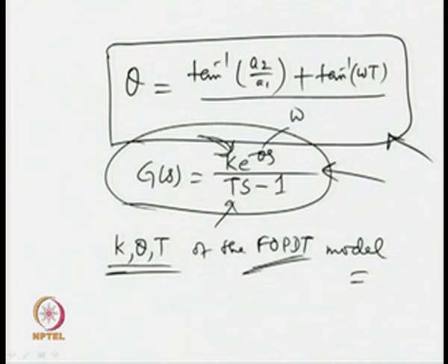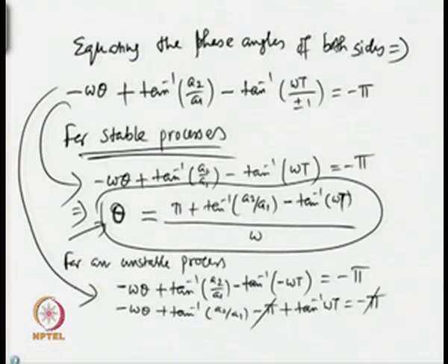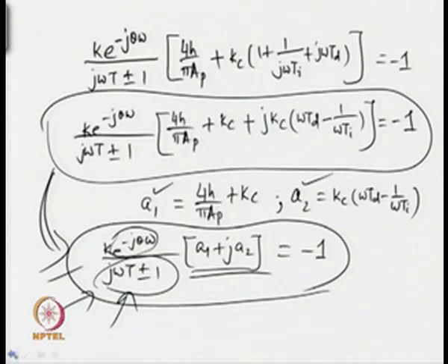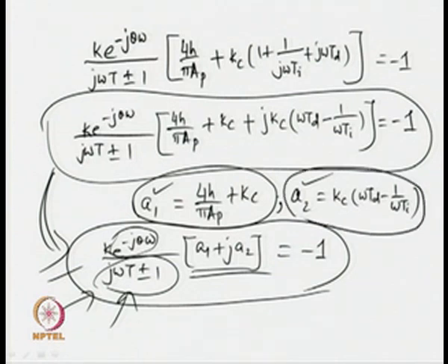Now, I will extend, now you see the constants. What are A1 and A2? If you carefully look at the two constants A1 and A2, you see it contains not only the gain of the relay, it contains parameters of the controllers as well. So, Kc, Ti and Td. Omega is obtained from the limit cycle output, but how to choose Kc, Ti and Td during the relay experiment or test, that poses a challenge.